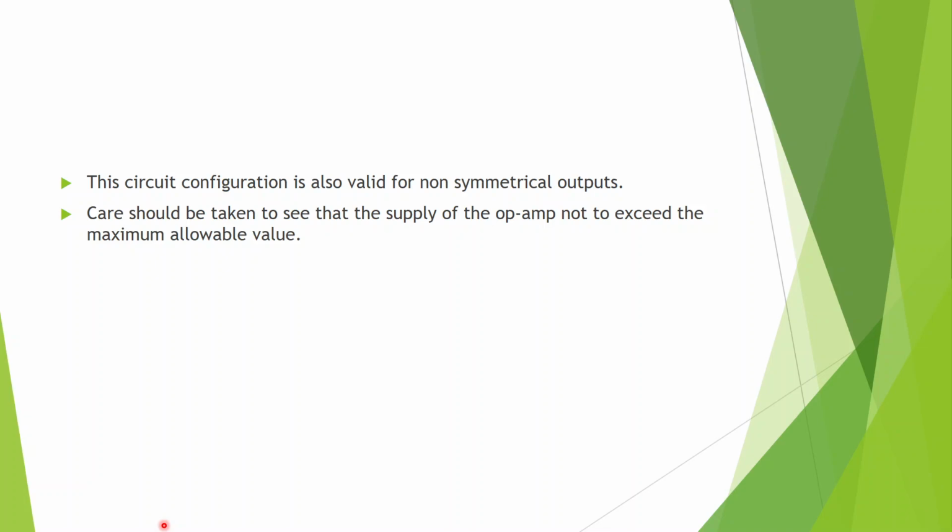The same circuit could be used for two non-symmetrical outputs. The outputs need not be of the same value. We have to take care that the supply of the op-amp does not exceed the maximum allowable value.